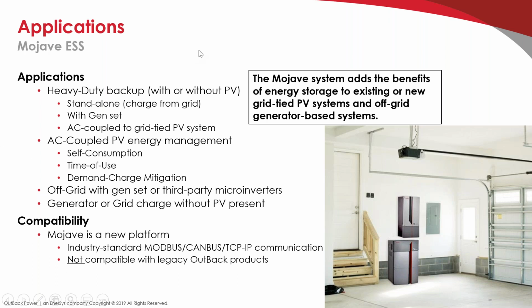So as Chris mentioned, this is really the only AC coupled product that I know and that our application engineers have said they would recommend for off-grid use. And there's different reasons to do that. If you want to have module level power electronics, that's probably the easiest and least expensive way to go about it, is to put in this with something like that. And so it'll treat the battery just fine, as opposed to having to be DC coupled. So the main difference here is we've really done a lot of work on the AC coupled side of this, and it controls that output just as well as a DC coupled product does.